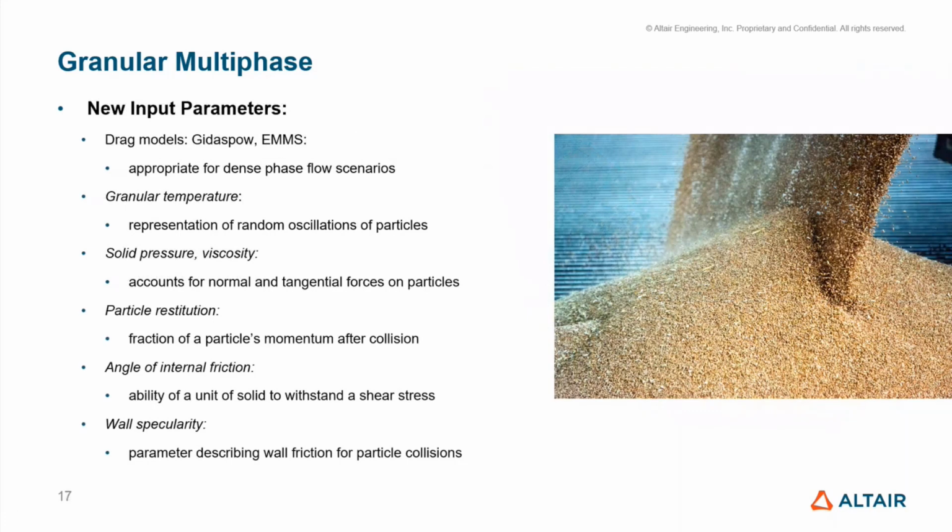The new physics that come with the granular multiphase feature include new drag models for dense phase flow. We've had the Gidaspow drag model from previous releases, but the EMMS is a new addition, and both of these models are appropriate for dense flow.